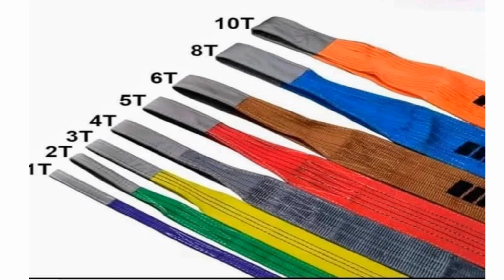So if you are a new employee, you have to be authorized before you use the EOT crane and web slings. As basic knowledge, you have to know which size of web sling to use and which capacity it has. Estimate the load first, and after that calculate the shape, sizes, and length, everything. Then you use the web slings. This one 1 ton, 2 ton, 3 ton, these slings are identified by the standard colors.